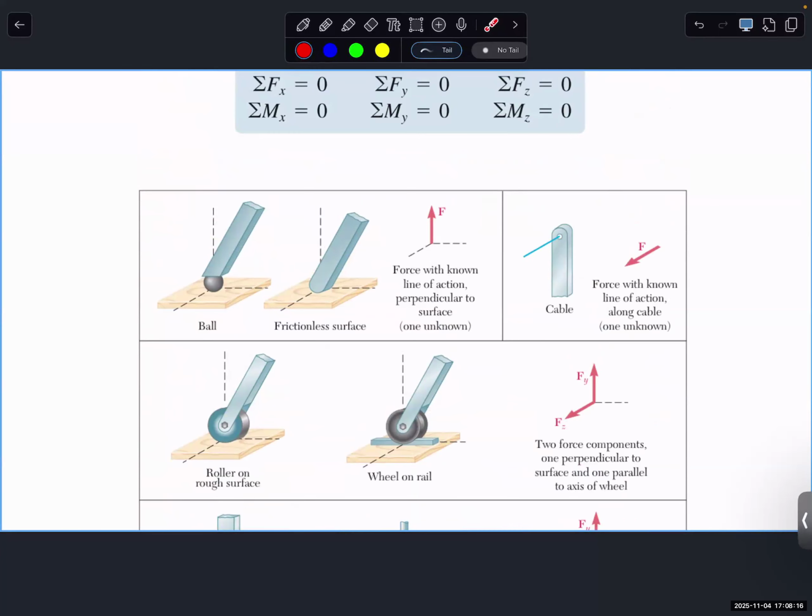If we have, let's say, a muscle or a spring or a bar, it's the same thing mathematically in the FEA. So you apply tension and compression. I can apply a huge force, but at the same time, I can increase the cross section. It doesn't mean that it will fail. A larger force doesn't mean that it will fail earlier, because I can change the cross section and make the force intensity lower. And the same thing, if I apply a small force, it doesn't mean that it's safe, because if I keep minimizing the cross section, the stress, or let's say the force intensity, can actually increase